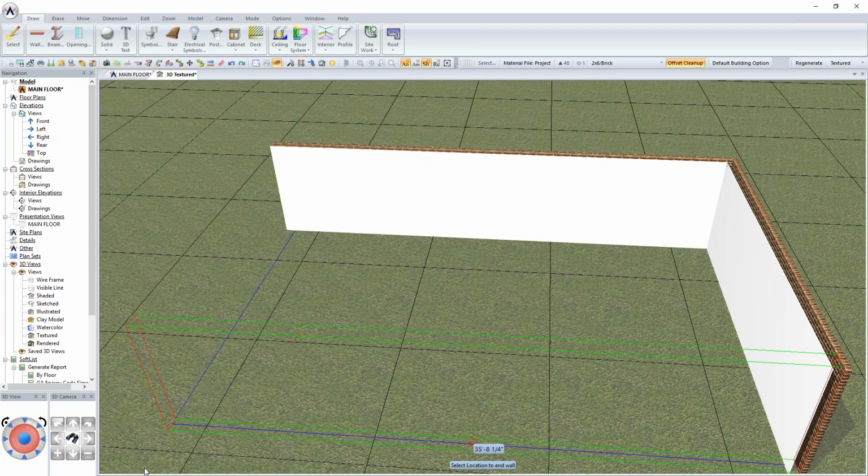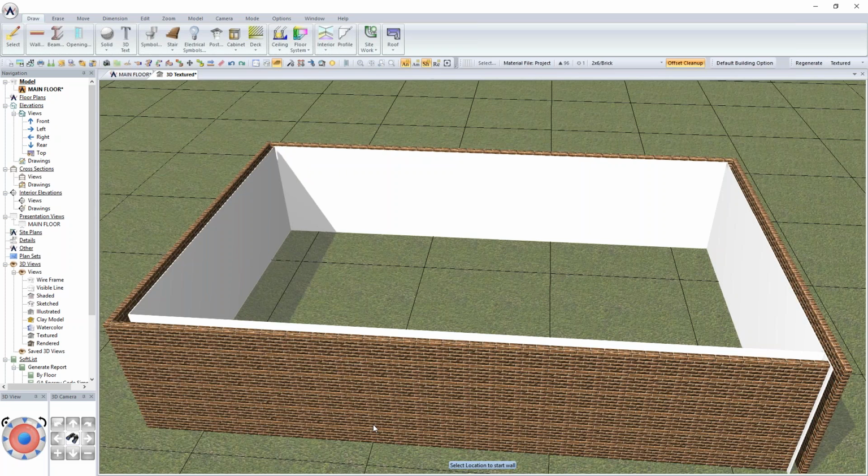I have the blue lines which indicate the direction and the ortho snap. And as I move this wall, watch as I move it left or right, when the blue line disappears, it tells me when I've hit the end point or perpendicular to that corner. And so I can then click and run this cursor up to the wall and click. And so in a quick method, I've now got some of my walls drawn.